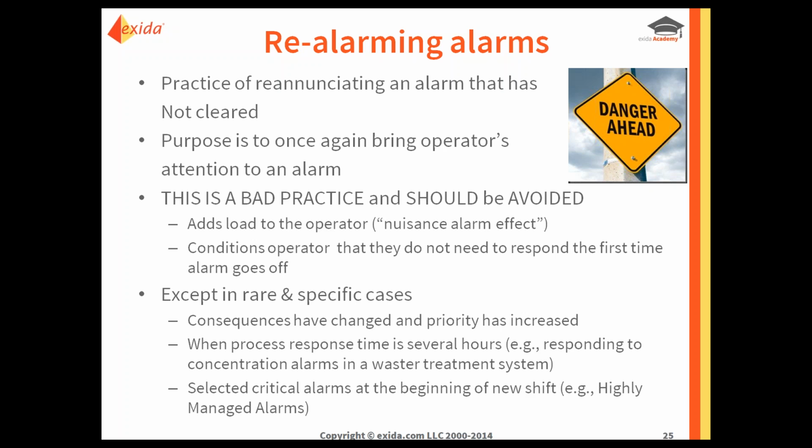And that is true. And that is why this is not a recommended approach. This is a practice that in general should be avoided. Why? Well, hopefully it's kind of obvious, but certainly it adds load to the operator, so they're getting more alarms. Part of what we were trying to do previously as part of alarm management was to reduce the alarm load on the operator. Well, using re-alarming alarms is only going to increase it.